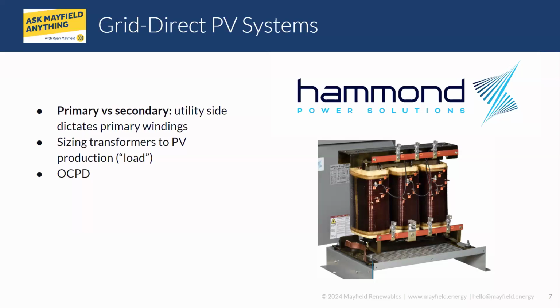So you could oversize the transformer, but there are some things that are not going to be adequate for the harmonic content even by doing that, like the rating of the neutral and the electrostatic shield and other things that help the transformer perform like it would in a normal environment, even with high harmonics.